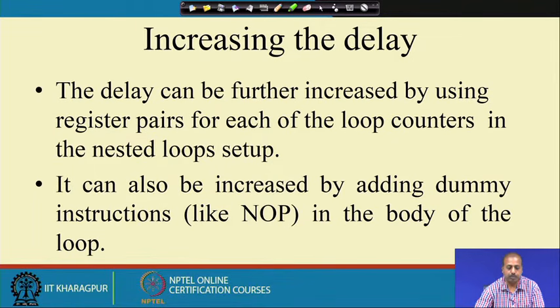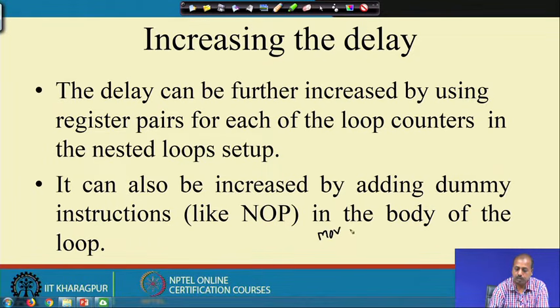For that purpose, we can put in an instruction which does not have any effect, like this NOP type of instruction. We can think about different NOP type of instructions, like I put an instruction like MOV B, B. Effectively it does not do any operation, any computation or any movement as such. So it is similar to the NOP, but this NOP is much more understandable. Many a time we put these NOP instructions inside the delay loops to increase the delay.